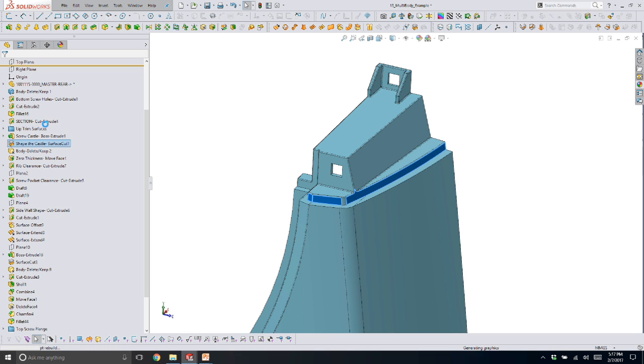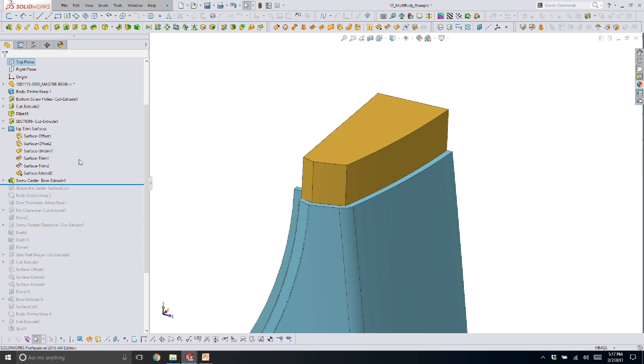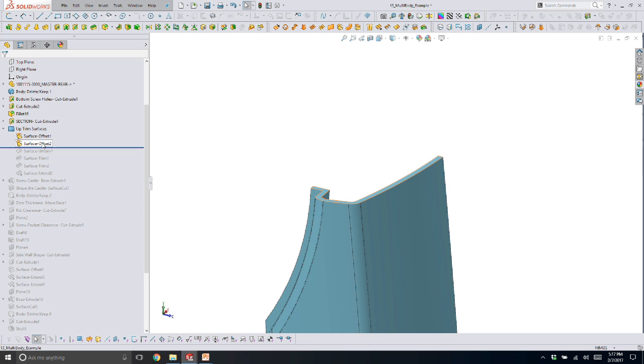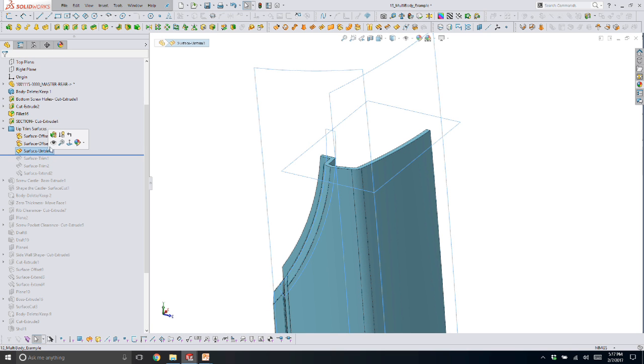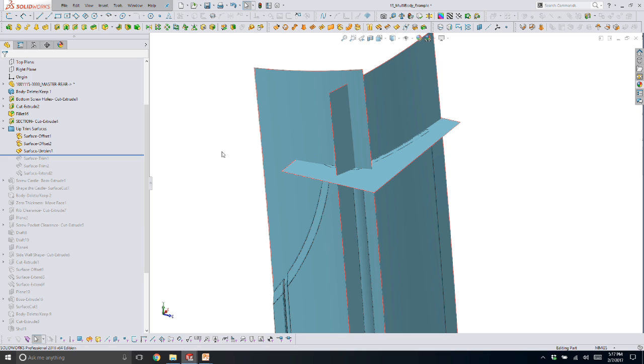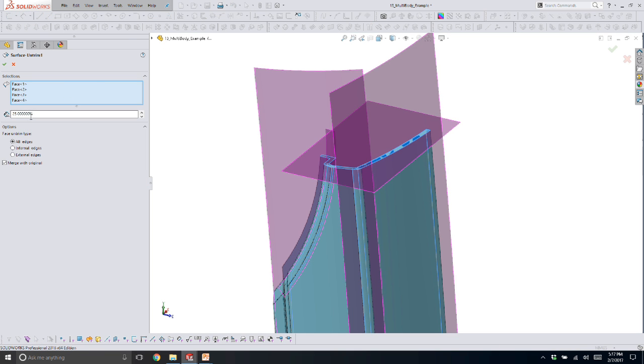So the way I did that was I used the offset tool to get my clearance, but the offset wasn't quite big enough. So we needed to actually add material to our surface offset. And that's where surface untrim comes in. So we used untrim before to reveal the original sides of the surface for creating our non-planar lip. But in this untrim example, I can actually make surfaces bigger by increasing this percentage. It's got a distance icon on it, but it's just a percent.